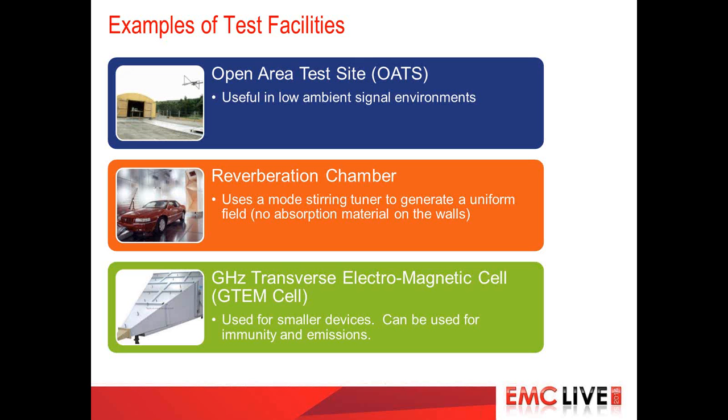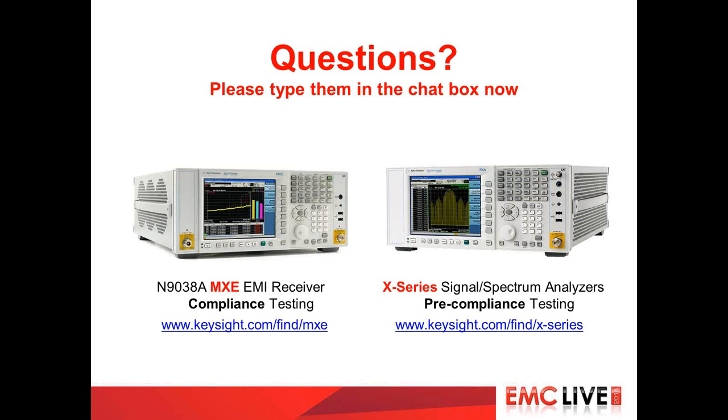It's essentially the same thing as a resolution bandwidth, and resolution bandwidth is the IF filter. Basically, we're down converting, and then the signals get filtered through that. But that's just the term that they use. Those terms are synonymous. So when we looked back earlier, the 200 hertz, the 9 kilohertz, 120 kilohertz, 1 megahertz, these are all the reference bandwidths or resolution bandwidths that CISPR defines and requires.